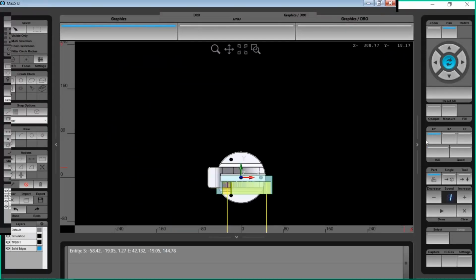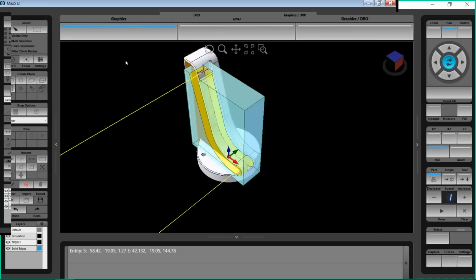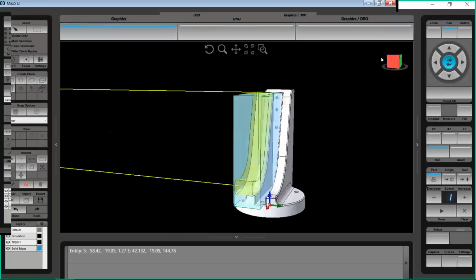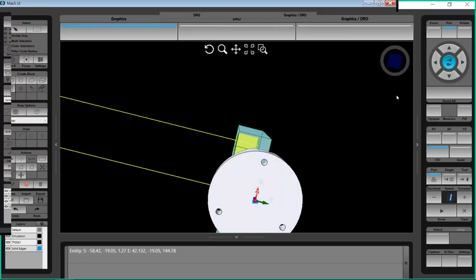Now notice that the top view is this way, but when you use sidewall contour, it goes ahead and applies a transform plane so that you can flank mill a wall that may not be in the current XY orientation. So it's not just flat features and holes that will get these transform planes, but we can also specify sidewall contours, and then we could add multi-passes in there or add additional pieces of geometry to that contour.